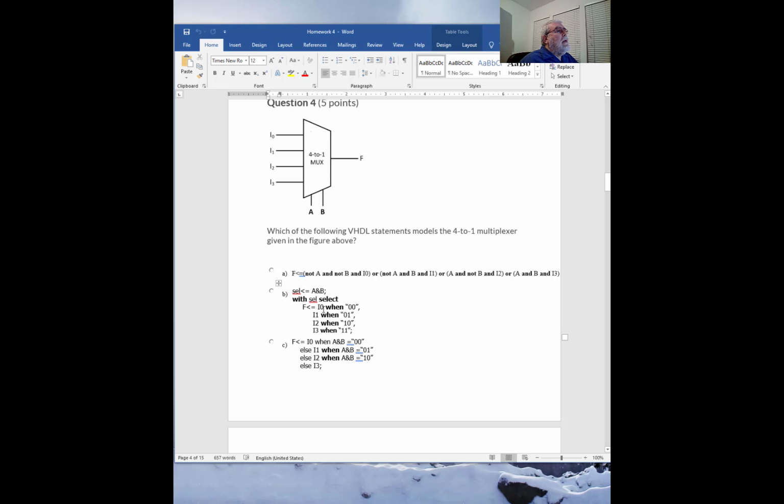How about this one? Well, if you look in here, we're using a select statement. And with that, we're also using this appending symbol, in which what you do is put these two things together. So A and then ampersand B means that the two things are allocated, one adjacent to the other. All right, this is append in this case.